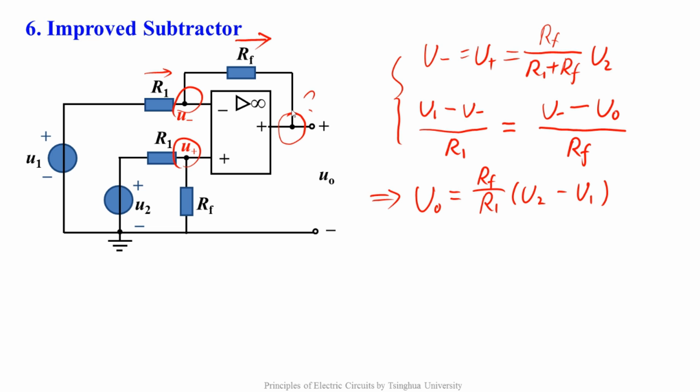But there is a problem if we apply KCL on the ideal op-amp's output terminal. None of the ideal op-amp's two properties, virtual short and virtual open, can tell us the output current of the ideal op-amp. Since the output current is unknown, we cannot get the relationship of the currents through other branches by KCL on this point. So generally, we don't apply KCL on ideal op-amp's output terminal.